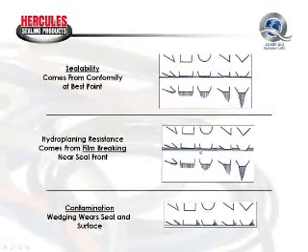With the round lip, we again have more fluid getting underneath the seal lip. Same is true of the square lip and the scraper lip. Square lip and a scraper lip, it's rare that you would ever see these used in a rod sealing application. Used in a piston application, like a piston cup or a Teflon type piston seal, you have a little fluid bypass at very low pressure. Typically have no problem with it in a piston sealing application because the fluid is contained inside the cylinder. But you would not want to use these for a rod sealing application.